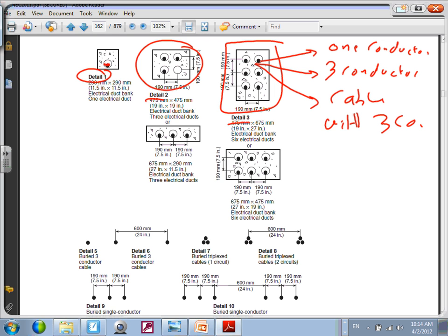It's a system though. They're not in one pipe. They're all in close proximity to each other. And this is for high voltage too. And you're absolutely right. How can I put phase A in one? The reason why you put phase A in one duct is because the conductor becomes so huge, so big, that you really can't put it in one conduit. But they're in close proximity to each other. They're supposed to cancel the magnetic field. You're absolutely right. What happened, Chad, to putting them all in one conduit?